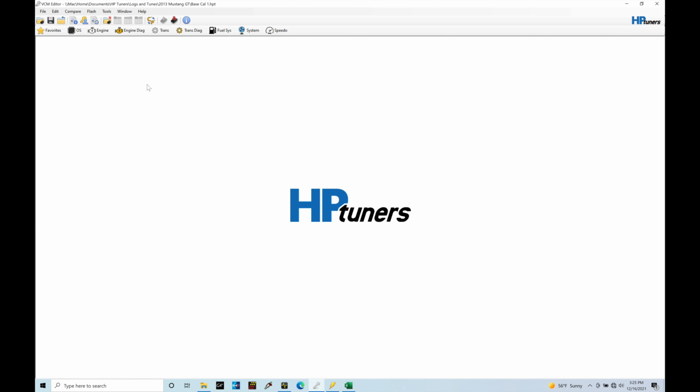This is going to drive the closed loop behavior and the reporting of the lambda measurement back to the ECU so it makes accurate changes in closed loop. If we have bad data in, we'll have bad data out. So we want to make sure that we're providing good data into the PCM whenever possible.